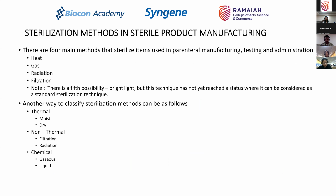However, just so that everybody is on the same page, we are talking about 4 main methods which are used in the sterile manufacturing process. One is heat, which could be dry or moist; gas, which could be ethylene oxide, hydrogen peroxide, ozone; radiation, which is gamma or electron beam; filtration, which is a physical form of sterilization.